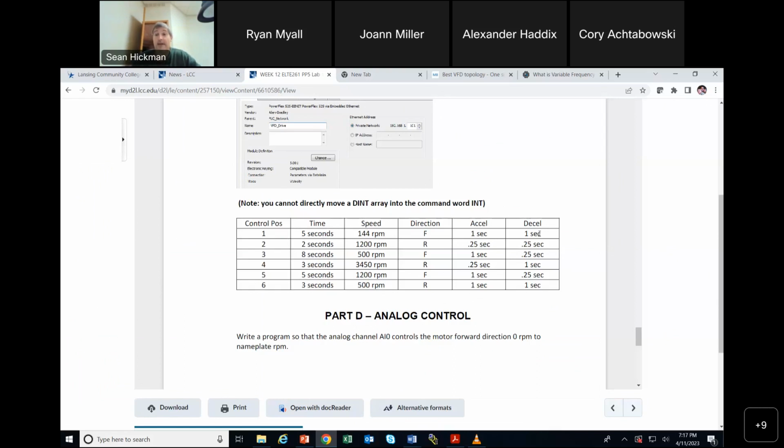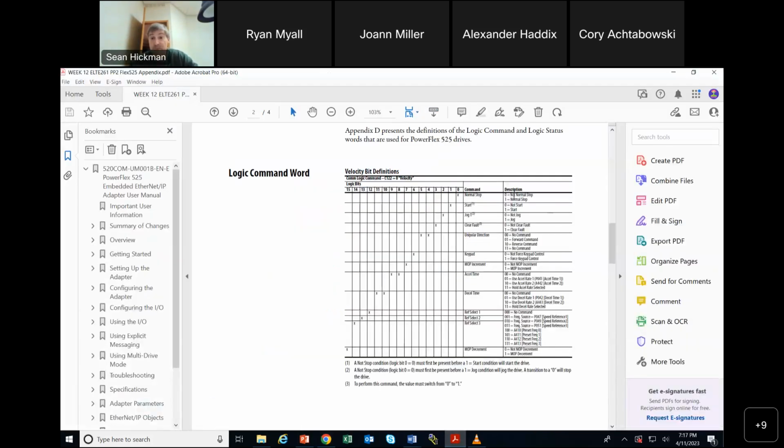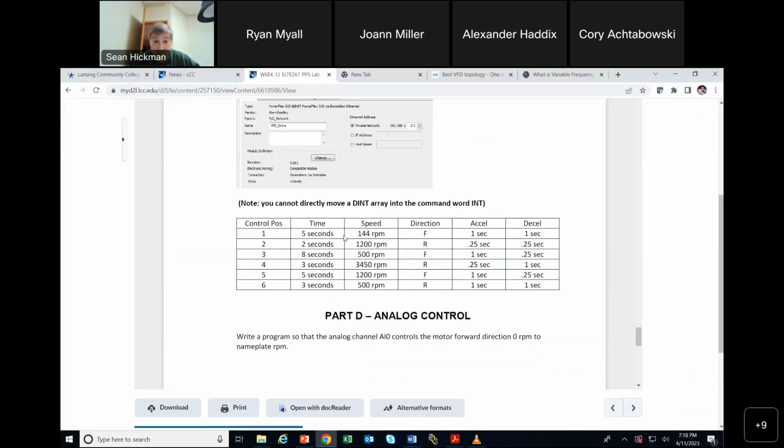All right. Next, ready? You actually have to stop the sequencer in order to do the next word. Robert, is that right? Did we get that part working or not? The sequencer has to be given a stop command in order to be given this next position, okay? Which means that you're going to have to come in with a word that's got a 0 here and a 1 there, and whatever else you got here, for 2 seconds before you go to the next word here. All right, and then you got to throw in that same word again for 2 seconds. You got to come to a complete stop before you throw in this word. So it does want a complete stop before it takes the next run word.